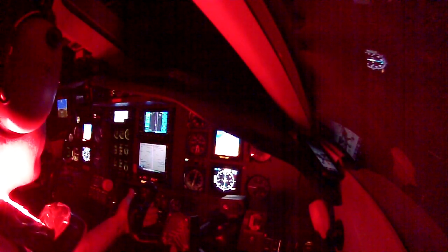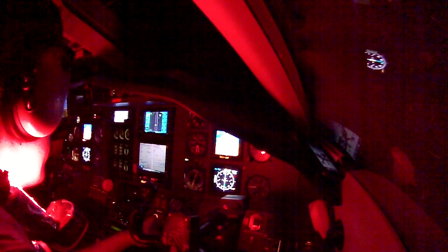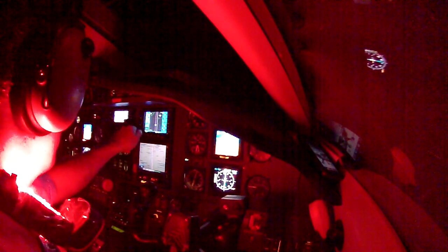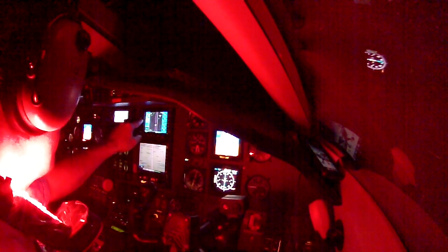So let's assume you want to know where Fort Wayne VOR is. Actually, let's call it Mansfield VOR, 108.8. You're going to select 108.8 over here, and you're going to go nav.